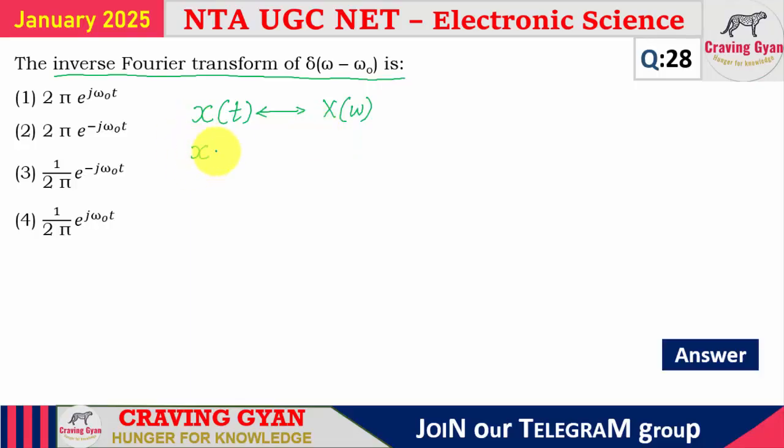Similarly, if you are performing time shifting, nothing but x of t minus t naught, what you will be getting? See, shifting in time domain, nothing but x of t minus t naught in the case of time domain will be exponential in frequency domain, nothing but x of omega into e power of minus j times of omega into t naught. Very, very important.